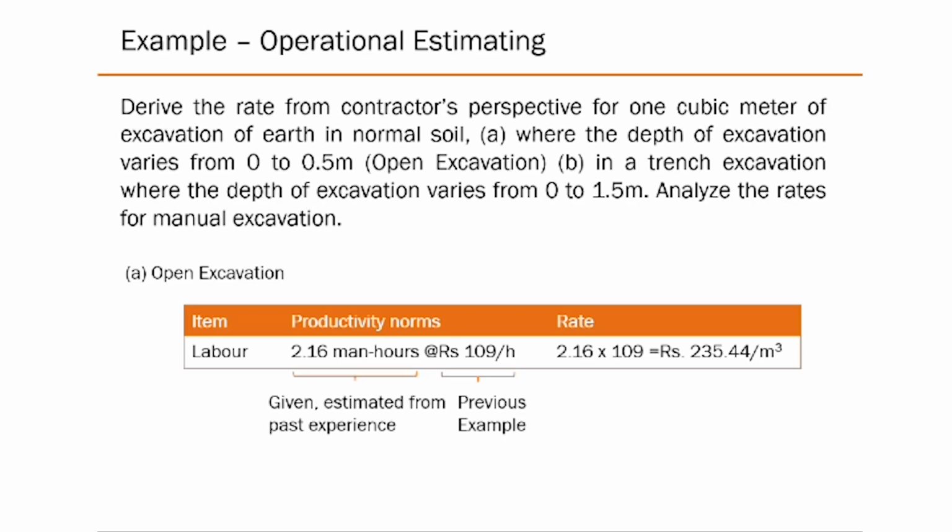And then we went on to start the concept of unit rate estimating. The idea being that once you know the unit rate of a particular activity and you know the total amount of that activity that you have to do, the total cost will be the unit rate multiplied by the quantity, and then taking the sum of all such items, right?